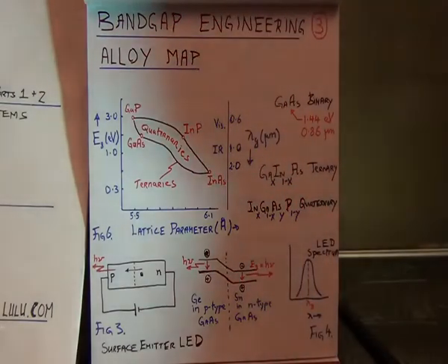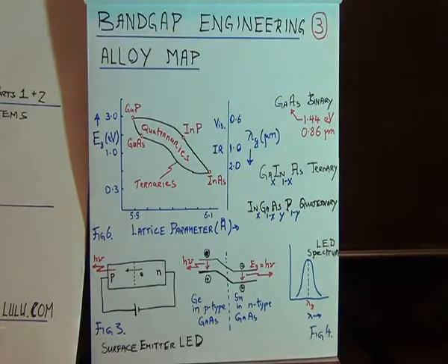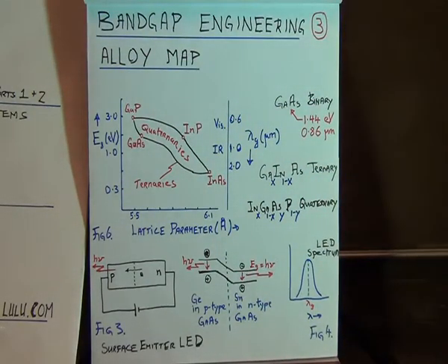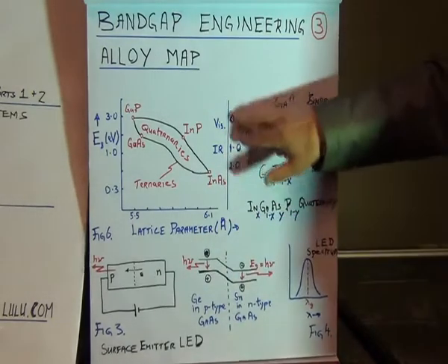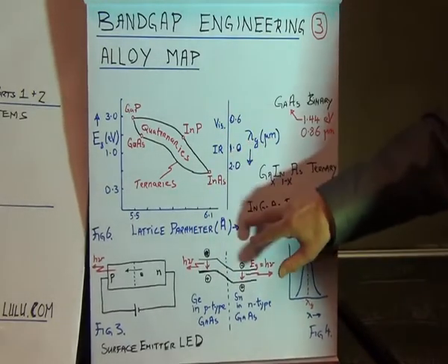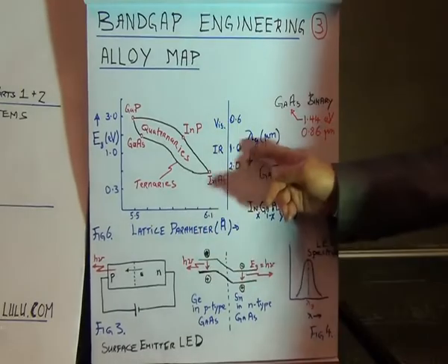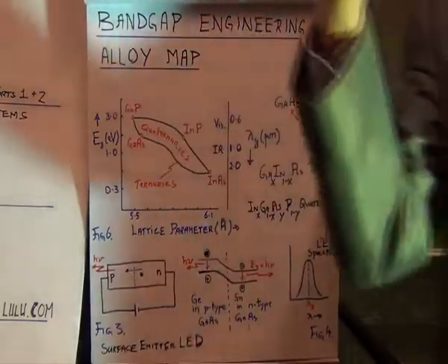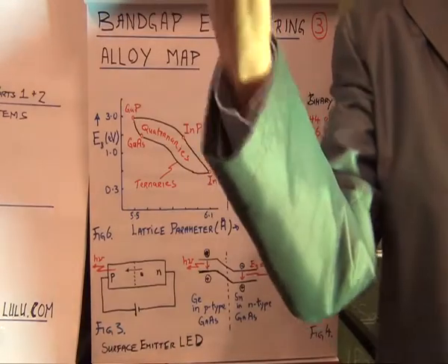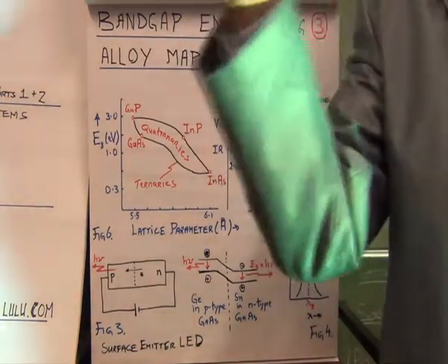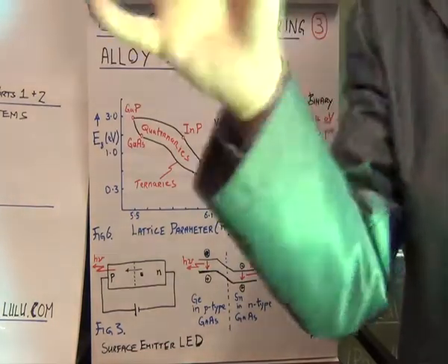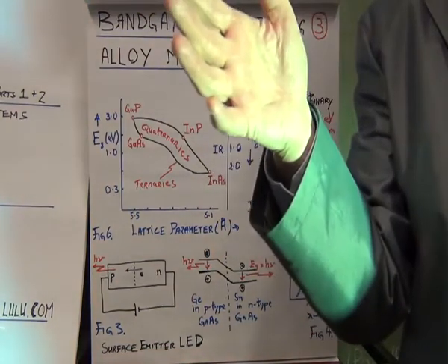And remember the end goal now. If I had been in charge of that last experiment, I would then take on the next PhD and say, now your job is to go to the wavelength axis for your thesis and work out a comb of 100 wavelengths in the C band of the optical fiber, all separated equally by 50 gigahertz in the optical frequency, say.